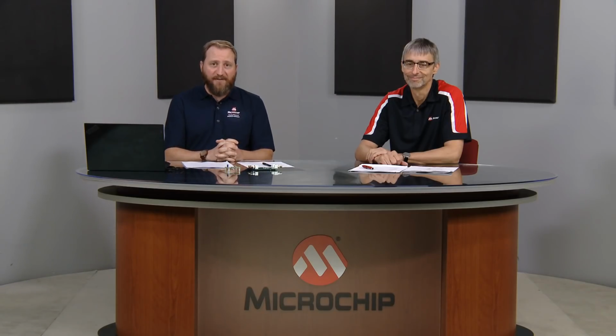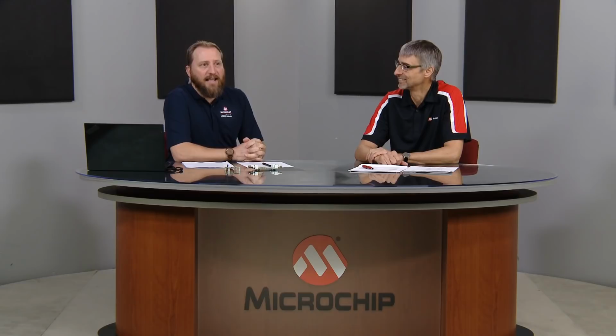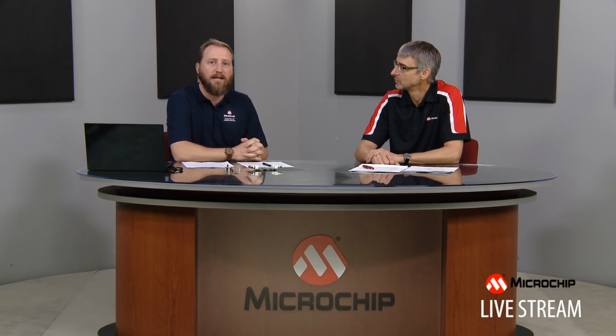Okay. So the question is, can a zero drift amplifier replace an INA? Well, that is a very good question. So, yes and no. Obviously, instrumentation amplifiers today, including those from Microchip, implement a zero drift architecture. So we already have monolithic instrumentation amplifiers that also utilize this zero drift architecture internally.